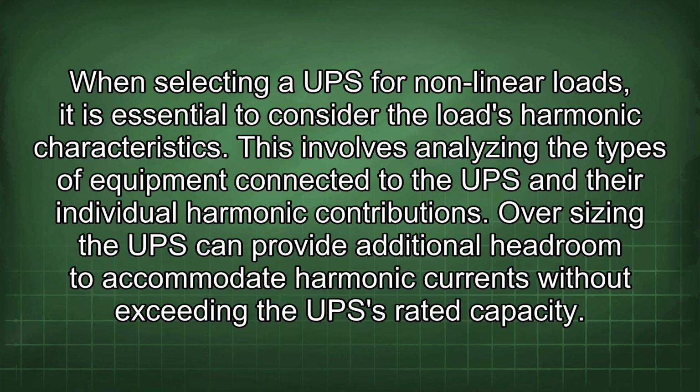This involves analyzing the types of equipment connected to the UPS and their individual harmonic contributions. Oversizing the UPS can provide additional headroom to accommodate harmonic currents without exceeding the UPS rated capacity.